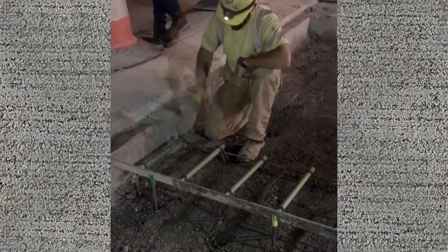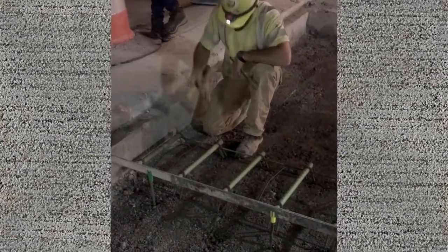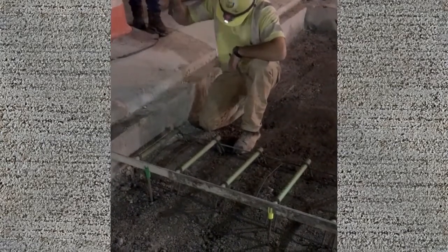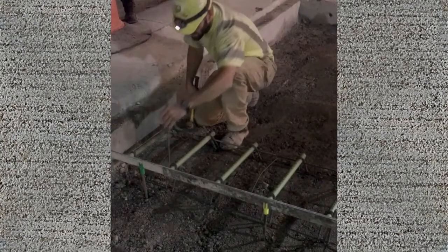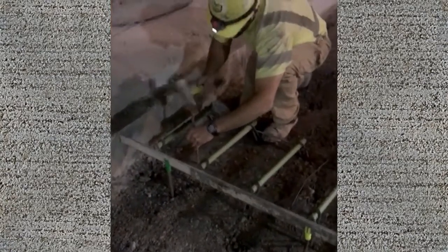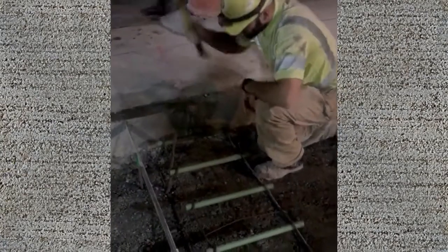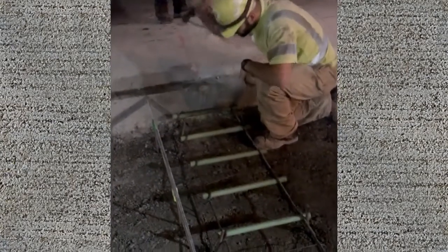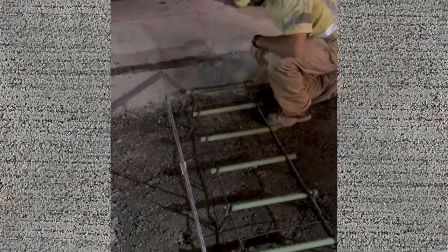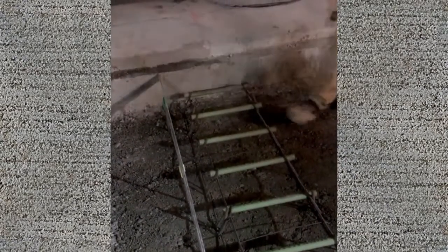New patch joint placement. Place Bulletin 15 approved dowel baskets at each transverse joint in the existing concrete pavement as shown in RC 26M. Place 8 anchor stakes in each 12-foot wide dowel basket, 4 on each side, to provide sufficient anchorage to prevent movement of the basket assembly. Make all joints normal to the center line of the roadway.